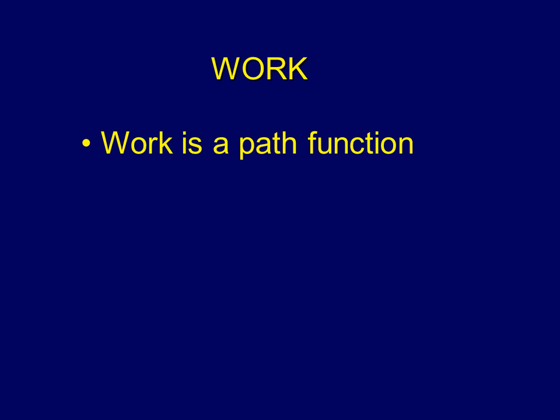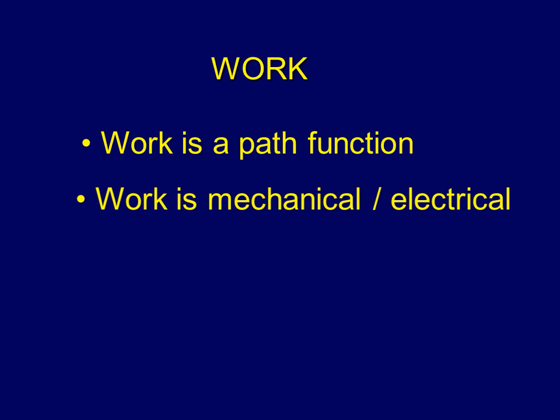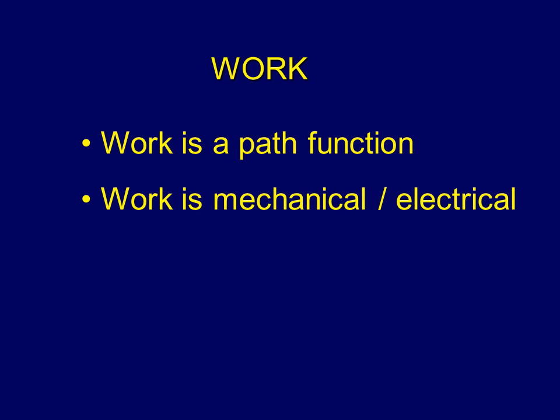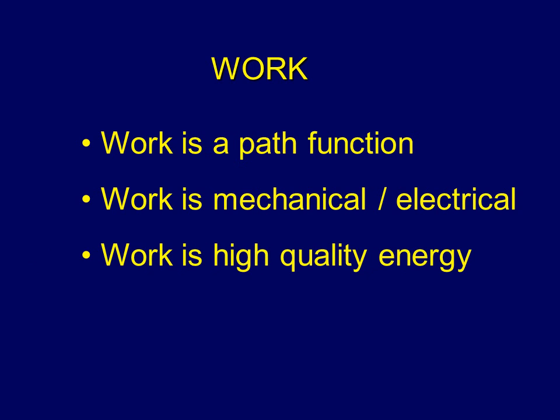Finally, another form of energy, going back to what we're going to review a little bit. So work is a path function. It's a mechanical or electrical form of energy. Work is high quality energy, and I alluded to that earlier. Basically because you can convert work into heat completely, but you can't completely convert heat into work.